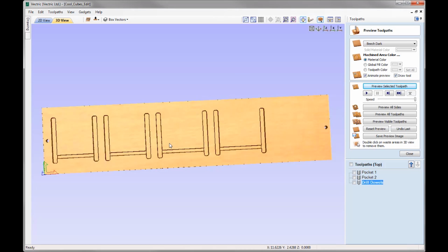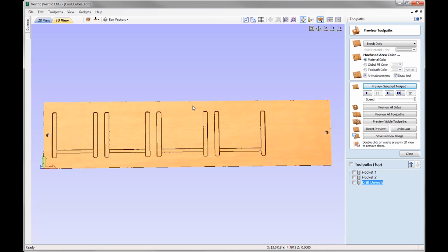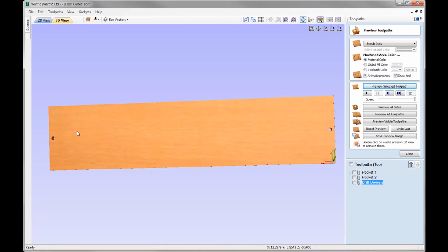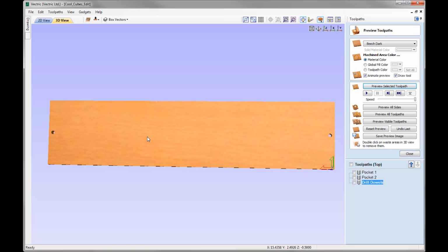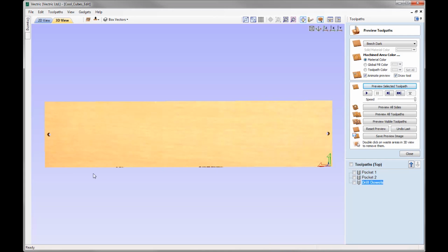So at this point, what we'd do in terms of the physical setup is we'd take this material block off of our machine bed, and we'd insert the dowels into the holes that have been drilled into the spoil board, and then we'd take our material and flip that over, and then we'd position that and align it to the dowel holes where we'd secure that in place. And because we've aligned it to the dowel holes, we know that our XY coordinates are going to be aligned with each other. And then we'd look at running the toolpaths for the bottom side.